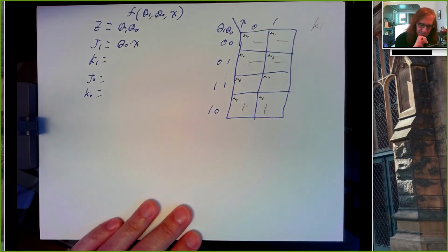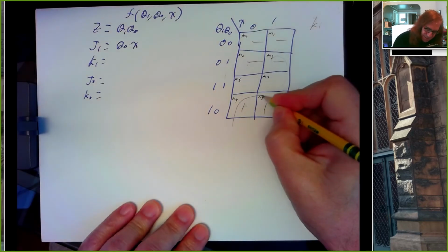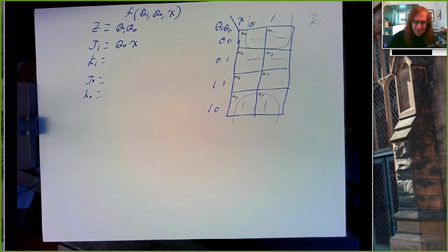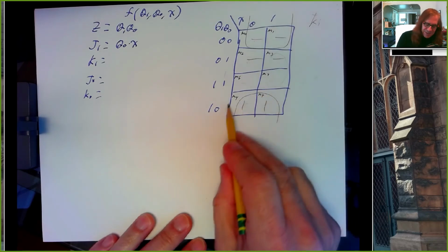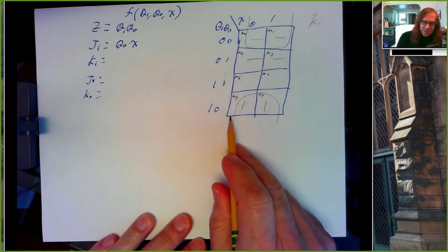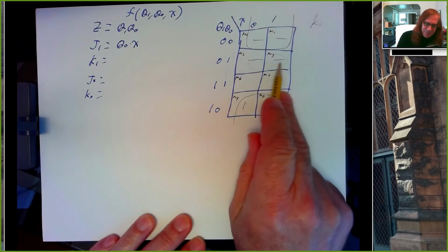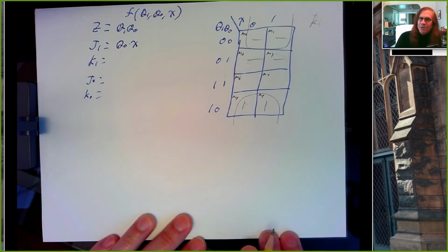Wouldn't it be best to do it with connecting the top half and the bottom half? I like it. So you have a 2x2? That looks really good. That's a nice big rectangle. It covers both of our 1s, but it's a bigger rectangle than just covering these two with a 1x2. Bigger rectangle, simpler expressions. So we don't care about these. We'll let those be zeros, but we're going to treat these as 1s.